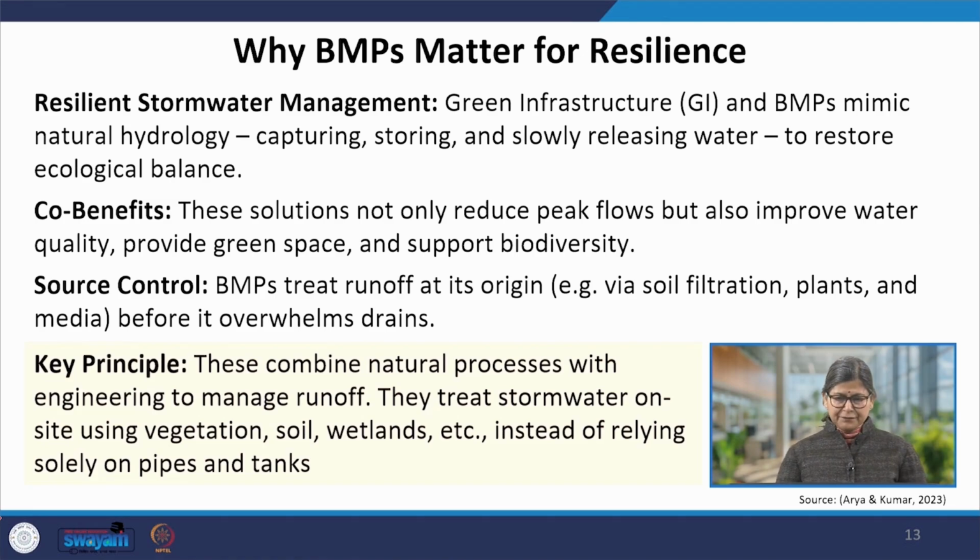Why BMPs matter for resilience? Resilient stormwater management, green infrastructure and BMPs mimic natural hydrology, capturing, storing, and slowly releasing water to restore ecological balance. And you can also use, instead of green infrastructure, the term blue green infrastructure. That is more holistic. Co-benefits: these solutions not only reduce peak flows but also improve water quality, provide green space, and support biodiversity.